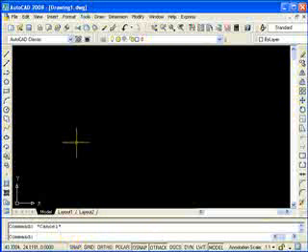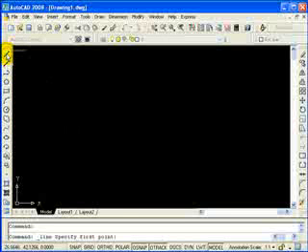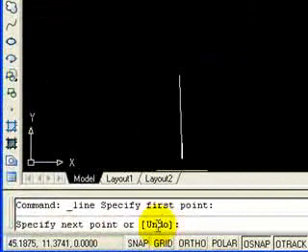One of the most basic commands in AutoCAD, obviously, is the line command, and that's where we first see our command line options. To start your line command, I'm going to go over here to my line button on my draw toolbar. I'm going to pick it, and it's asking me to specify my first point. I'm going to pick my first point, and after I do, you'll notice down here on my command line, AutoCAD says specify next point, or, and then it has the word undo in brackets. And one thing to pay particular attention to is the fact that the U in undo is capitalized.